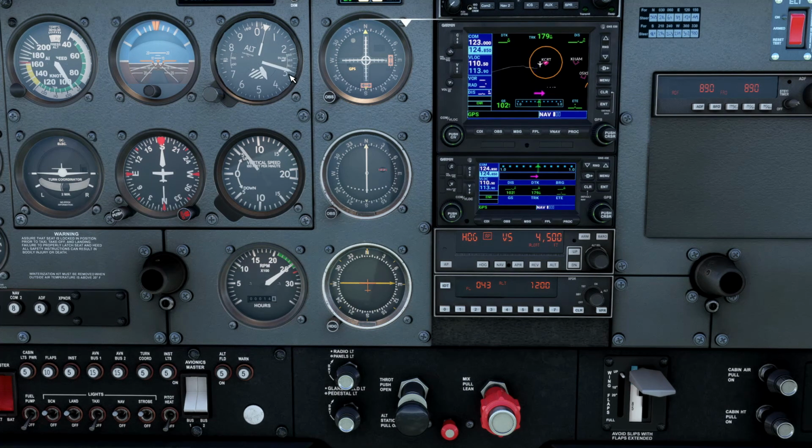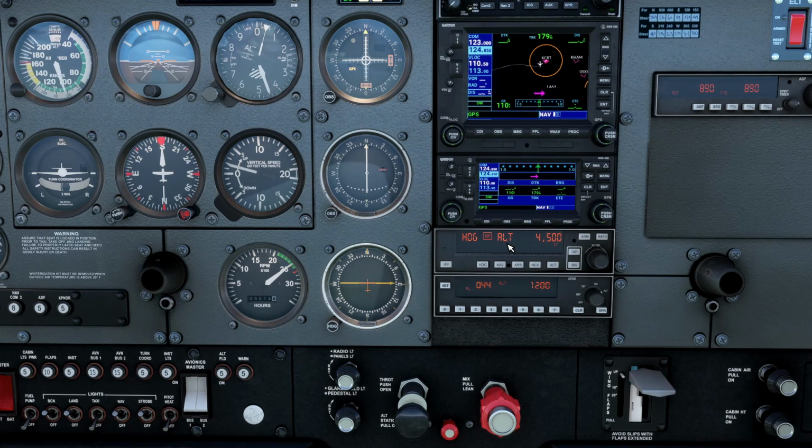So there's 200 feet prior, the altitude alerter goes off, and it has started to capture the altitude. You can tell it's gone into altitude hold mode now. It takes a little bit of time for it to do that last 100 feet. It really kind of milks that climb for the last couple hundred feet. And then once you're level at the altitude, don't forget to reset your power back to your cruise power. And that is how you do a climb with this autopilot in the 172.